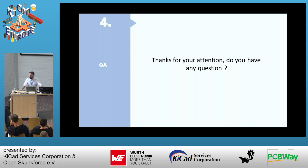What's your typical stack-up? To be honest, I have to check about it. We have a web page on our website with all our standard stack-ups. You can select, for example, the copper thickness you want and the number of layers, and then we have the possibility to share with you our standards. However, if you want a specific stack-up, it's also possible, but the price will be different because you have to modify our standards. But I will share with you the web page.